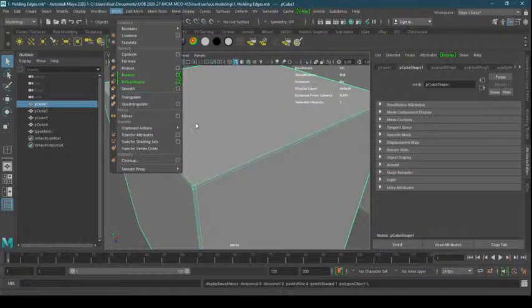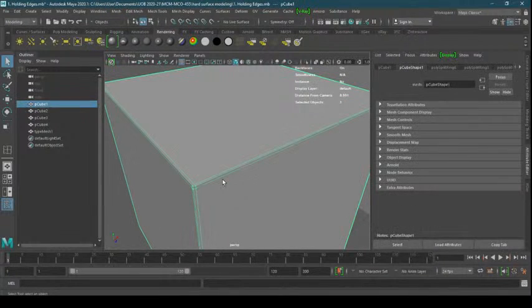Because 3 is only for Maya and it will only show me how it will look in rendering or in Maya, without making my computer slow. If I apply this smooth, I can export it, and in that other application the smooth modifier will be there. But this will make my computer a little slow. That's why I'm not using this one. I just press 3.